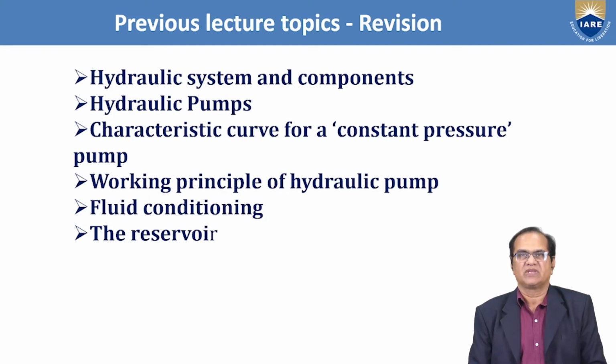the hydraulic system. Because if the hydraulic system is not there, the pilot has to apply forces which are always engaged, and a lot of energy is consumed from the pilot, and the pilot will get tired. To avoid that, hydraulic systems are used so that the pilot can operate the system by applying a very small amount of force, and the feedback received from the control systems is also reduced to a minimum level, so that the pilot will only have a feel of the control surfaces but not the real load which he would get if there was no hydraulic system.